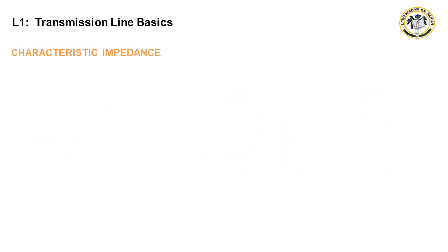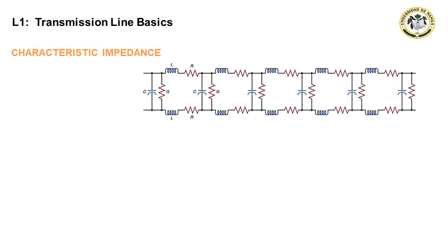When the length of a transmission line is longer than several wavelengths at the signal frequency, the two parallel conductors of a transmission line appear as a complex impedance. The wires exhibit considerable series inductance, whose reactance is significant at high frequencies. In series with this inductance is the resistance of the wire or braid making up the conductors, which includes inherent ohmic resistance plus any resistance due to the skin effect. Furthermore, the parallel conductors form a distributed capacitance with the insulation, which acts as the dielectric.